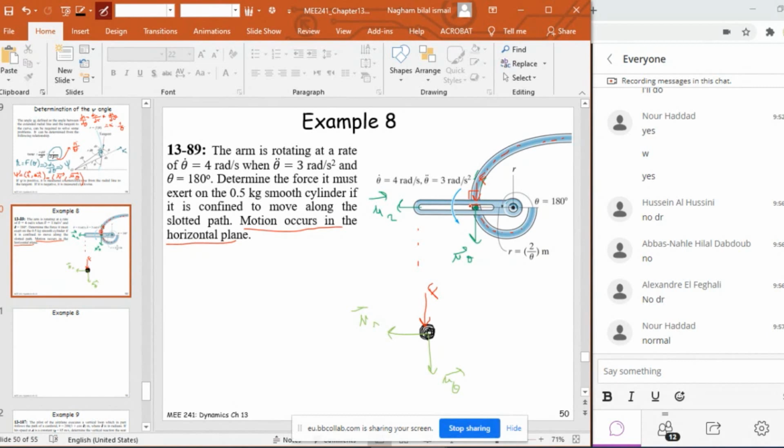Now, if I want to take the tangent at this point, this path has a vertical tangent here and an oblique tangent here. So this means that the normal force will be perpendicular to this oblique tangent. So this will be the normal force. Of course, you can assume any direction, and then from the values at the end of the problem, you can predict whether these directions are correct or not. All right, guys?